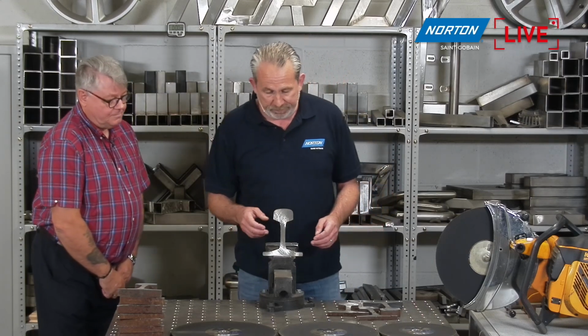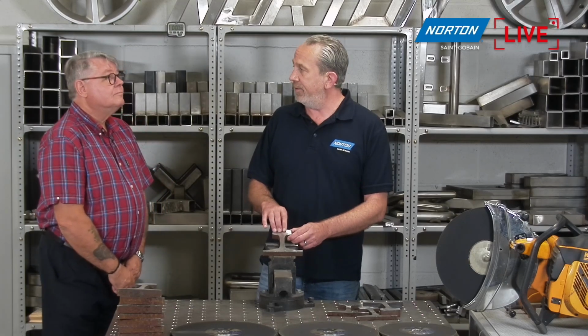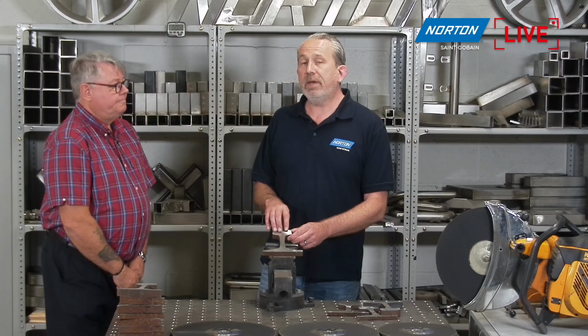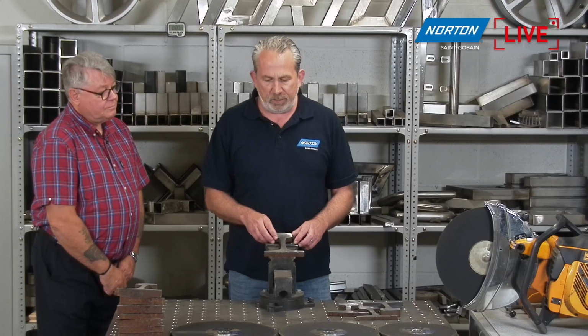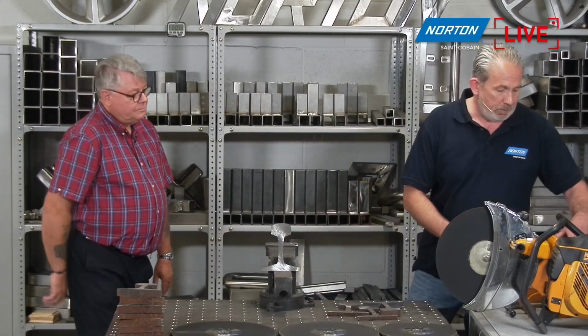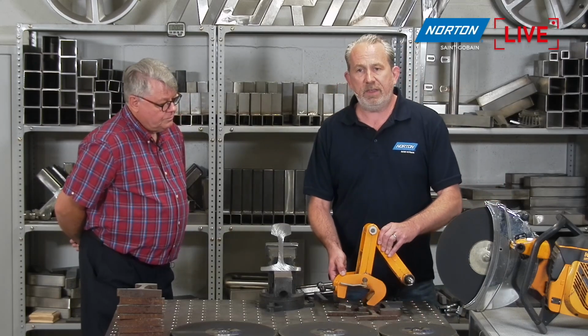It makes perfect sense. Okay, so we know the different types of rail we use. This is by far the most popular size, I would say. On main lines. On main lines, it's the UIC 60. Okay. And so when we were talking about cutting the rail, a few tips about cutting the rail. First of all, we were talking about the clamp. So we've got the machine here, and we can see the big petrol saw. But when we actually cut, we must ensure we use this clamp here.